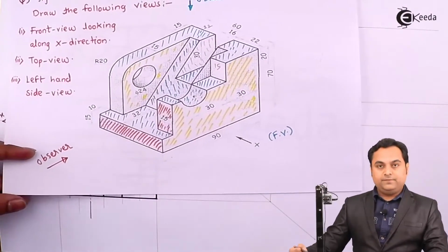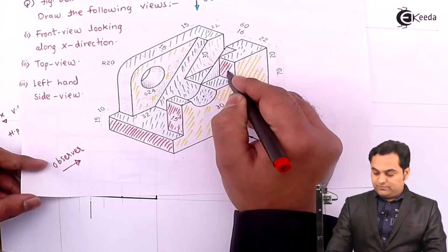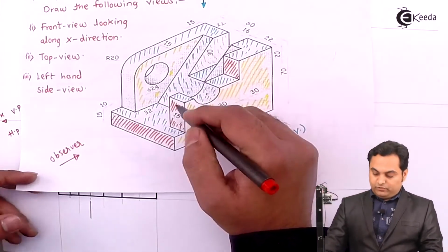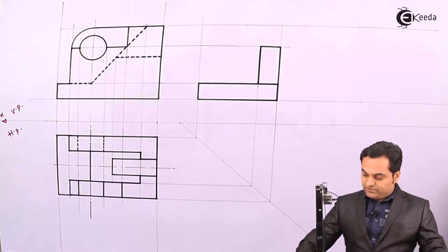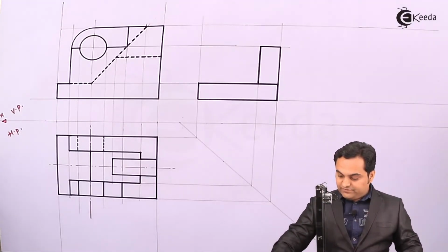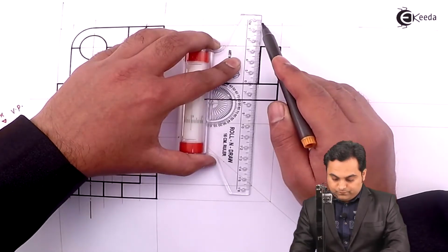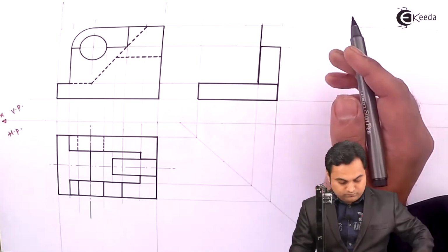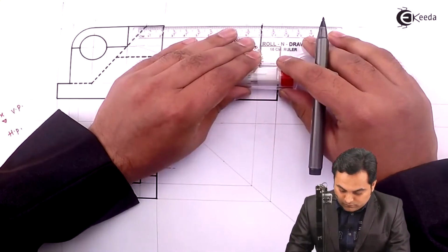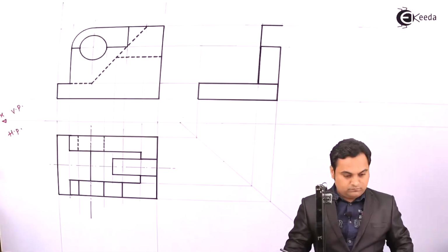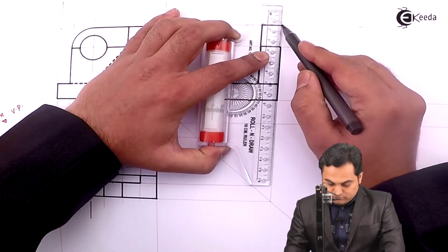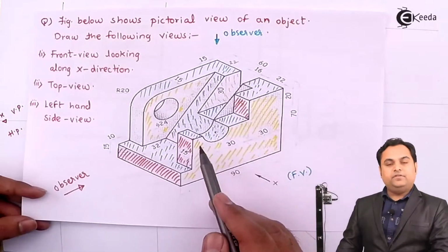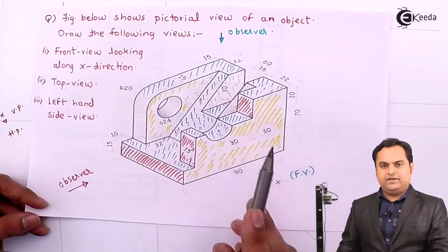Next, looking from the side, even the surface here is visible. So this is up to the top. It means whatever is remaining above is the same surface which I have shaded in the side view. So it would be made dark. So there is a dark line between these two surfaces. It means there is a change of plane. This portion is ahead, this is behind.